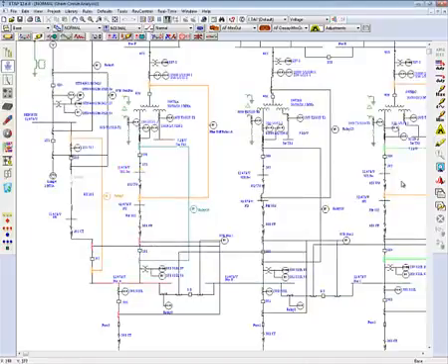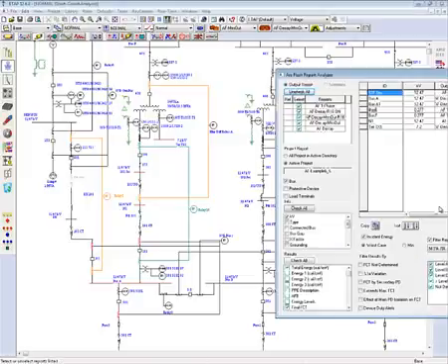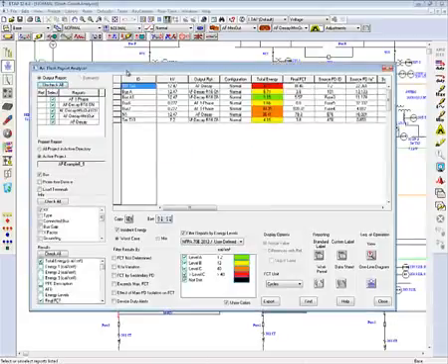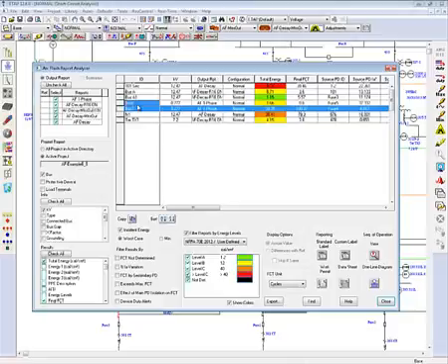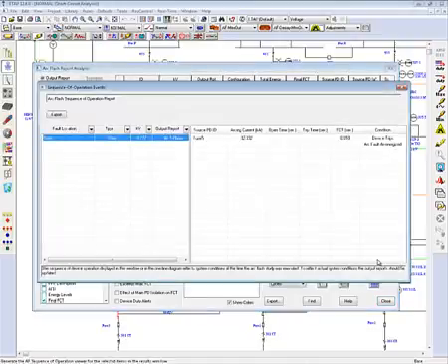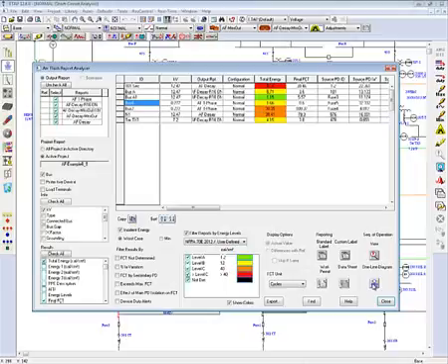Now finally, you can also view single phase sequence of operation events, but this can currently only be done through the Arc Flash Report Analyzer. What I'm going to do is go ahead and launch it, and I actually have my Arc Flash single phase case in here, bus 6 and bus 7, and I can go ahead exact same way as in 3-phase analysis, launch my viewer as well as my fault insertion.